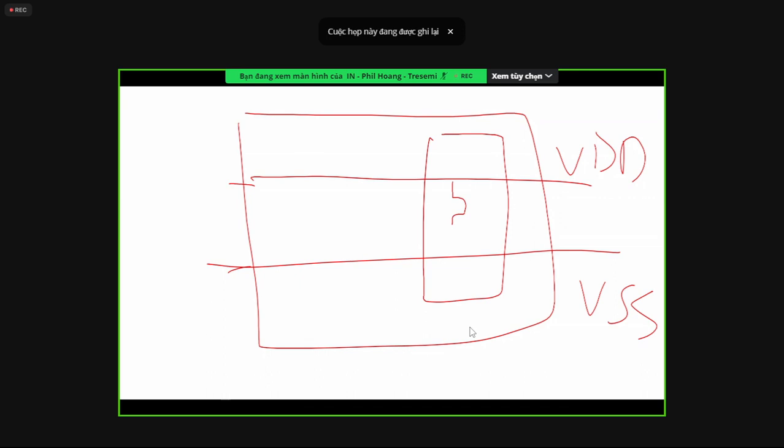If it draws too much power, then the R and the C going into it will create some kind of IR drop, right? So if you have a macro that draws a lot of current, meaning I is big, then if you put it away from the source, the VDD path here, then your R will be big.